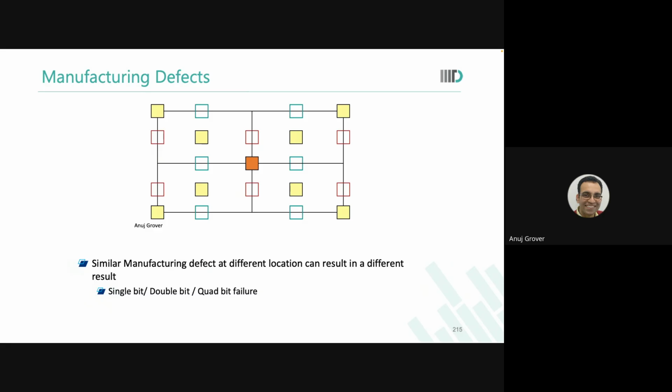It means that so many things that you did beyond the DRCs, anything of that could have failed. So the probability has already increased for you because you did DRC violations. So you better keep some extra repair elements in your system so that these vertical bits, horizontal bits, and quad bits, and even single bits, when they are coming because of process, should be repairable.